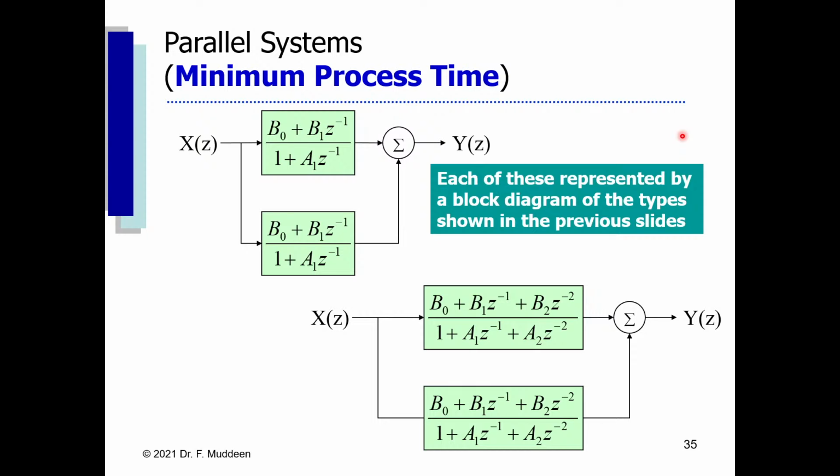The one that'll give you the most trouble would be the canonical form, because like I said, that's where the input and output directions are reversed. The inputs go into recursive and the outputs go into non-recursive. The direct form is the easiest one to do, because all the inputs are non-recursive and all the outputs are recursive in nature. So the most tricky one you want to look out for is the canonical form representation.